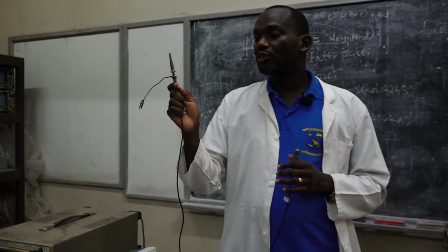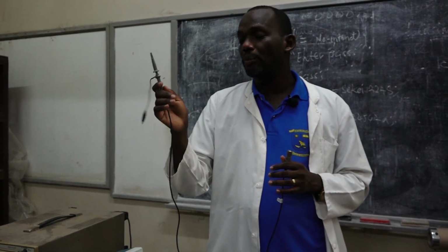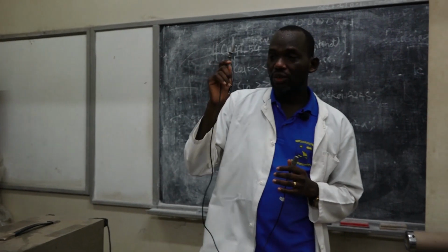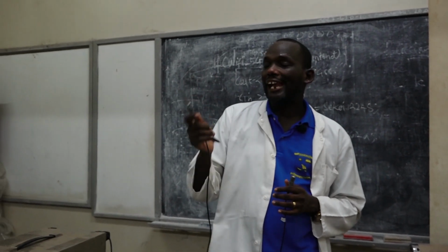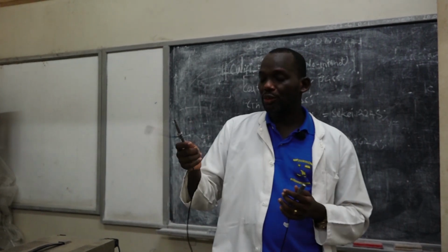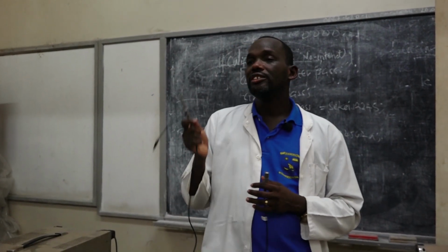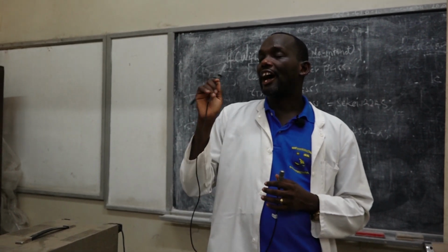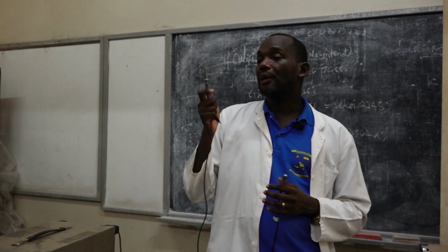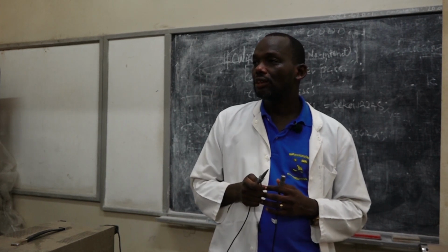Some oscilloscopes might need you to set the probe attenuation setting to times 1. And some digital oscilloscopes, or even analog oscilloscopes, might need you to set the attenuation to times 10. Are we together?